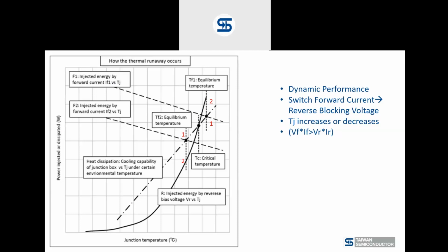In this case, the junction temperature goes down. That means the leakage current will go down and will continue to go down to either a stable value or to room temperature, or in the case of a switching power supply, it will just go up again when you are working in the forward direction.